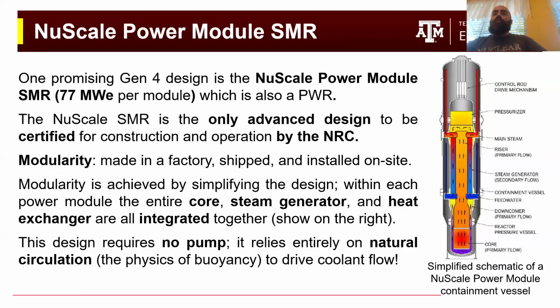In terms of some of the newer designs that are coming out, some of these Generation 4 Plus reactors, the NuScale Power Module is an SMR. This number actually might have changed. I know that at some point they decided that they were going to lower their power rating. But technically this is an integral pressurized water reactor, and it's called that because you have the core and the steam generator, basically all in the same pressure vessel.